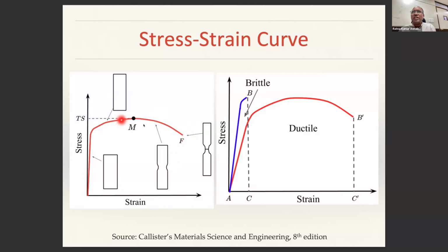Right? At this location, you will have something called necking that takes place. That means locally diffuse necking happens, and as a result, there will be damage taking place in the material. Because the material is getting damaged, the force required to cause further deformation reduces, and the original cross sectional area is not changing, and as a result, because the force is reducing because of the local damage in the material, the engineering stress reduces.